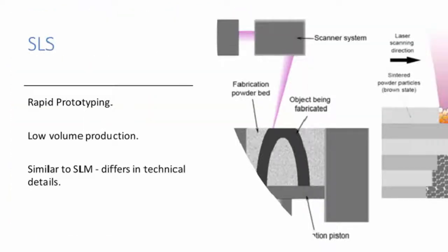Selective laser sintering, SLS, is an ALM technique that uses a laser as the power source to sinter powdered material, aiming the laser automatically at points in space defined by a 3D model, binding the material together to create a solid structure.